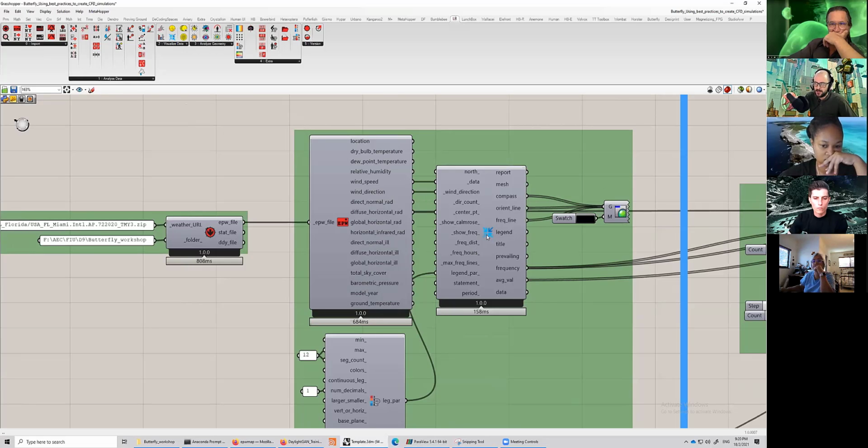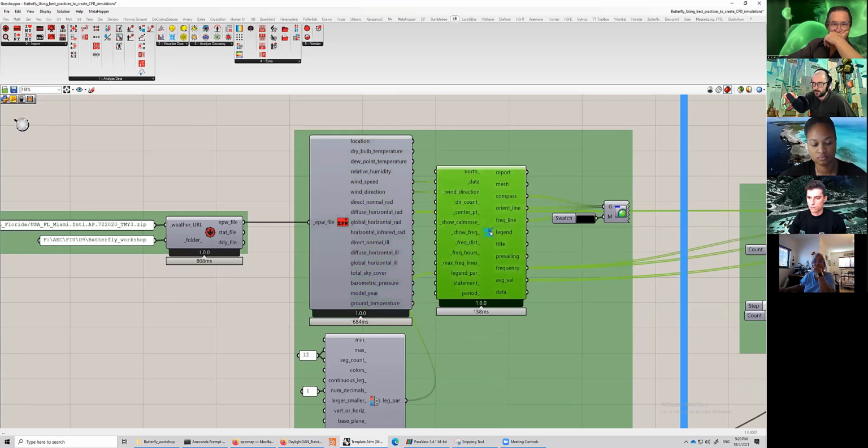And in fact, what I do is I use the wind speed and the direction to make a wind rose. And this is the first thing that you should check, right? To understand, okay, should I do a CFD simulation? Yes. And when should I do it? What is the wind direction that I should care about, right? And this component tells you all of this, and I will show it right now.